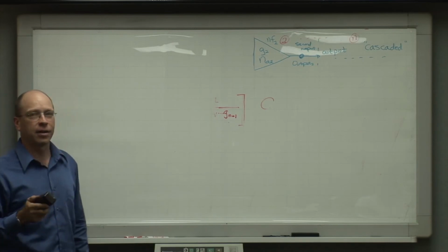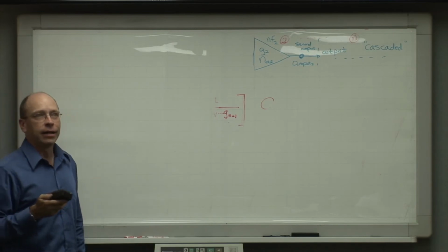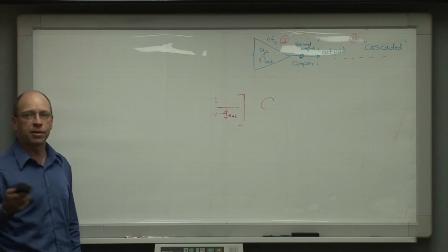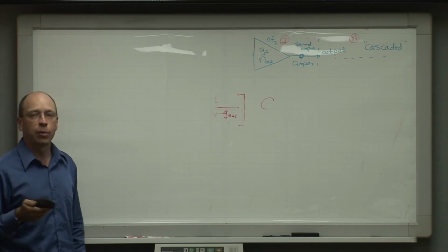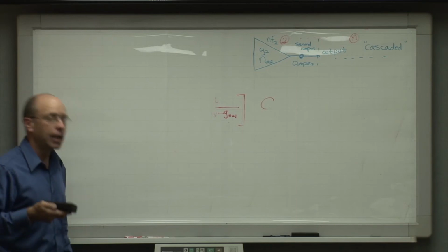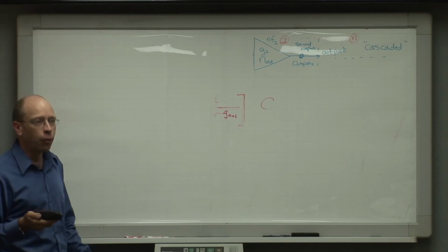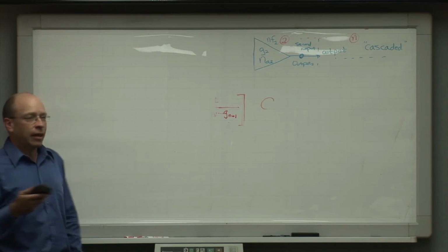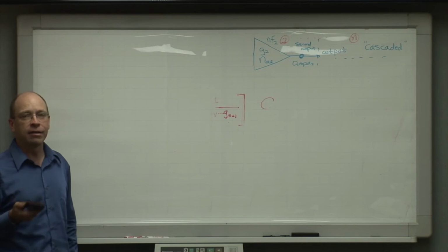I'll digress for a moment. People often think that if they want to see more signal, they need more gain. The problem with that thinking is you don't need to see more signal. You normally want to see a higher signal-to-noise ratio. As we'll see here in a moment, the problem with having more gain than you need in the system